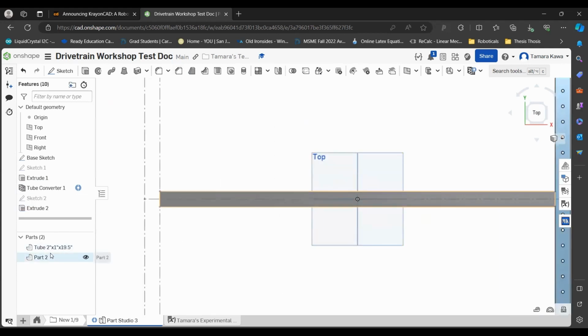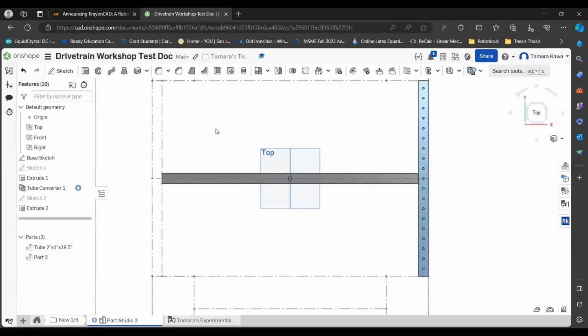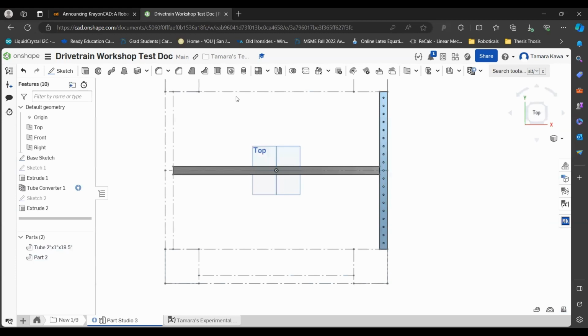See, and the nice thing about that is it creates something called part 2, and it's a different color. By the way, this is where I kind of just jump in here and say this feature script will rename the part. Not all feature scripts will do that, and I highly recommend you use something like the dimensions or a distinct feature when you're naming the part. Try not to use color, and try not to use something that you know is going to show up with other parts as well. Anyways, PSA over.